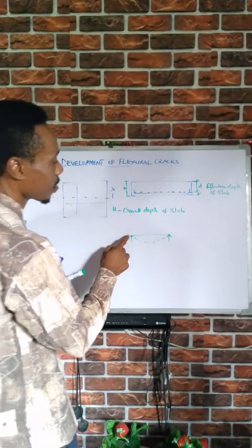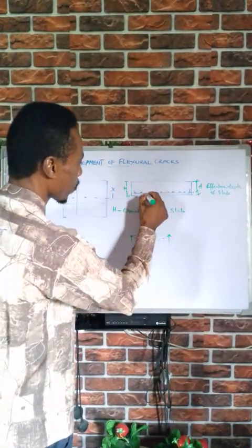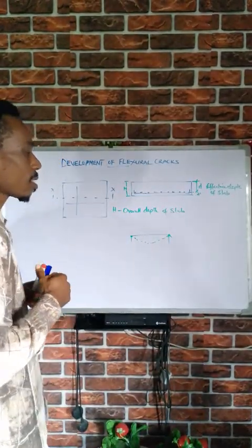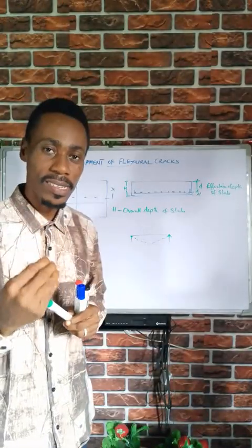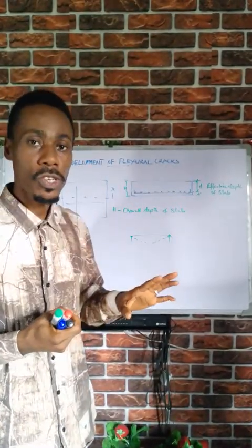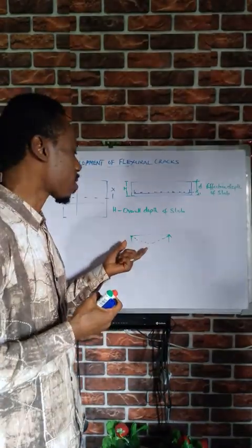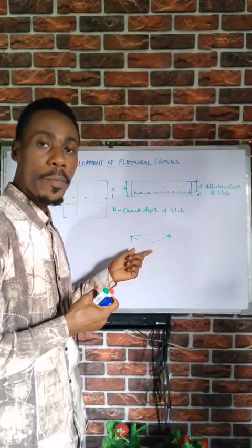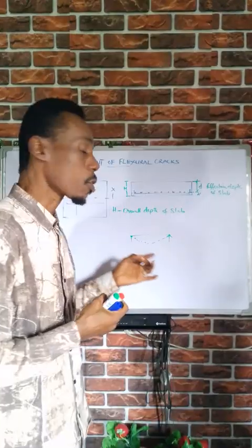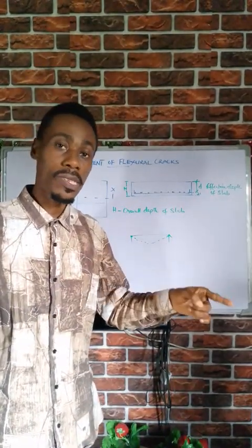This bottom reinforcement is what takes care of tensile stresses. Once the load comes on the structure, it tends to stress the main bar, the bottom bar, because in a one-way spanning slab it is the bottom bar that usually transfers the load to the supporting beams.